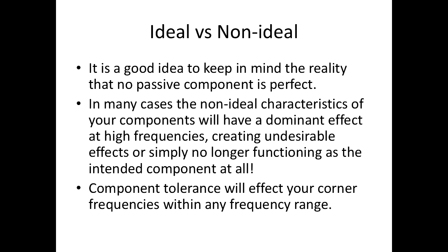So we take 1 gigahertz because of when the parasitic effect comes into the picture. Parasitic means when you have a resistor, you see only pure resistance, but it gets capacitor and inductor values when it is coming close to 1 gigahertz. And even in the capacitor, you will see inductor effect. All these things will come into effect. So that is called a parasitic. Even in the copper track, you will be seeing only the resistance or impedance value, but then it will have capacitance and inductance, all these values will come into effect on the copper track of the PCB when it is close to 1 gigahertz. So that is called parasitic components.